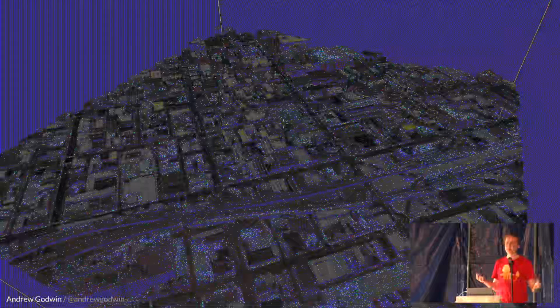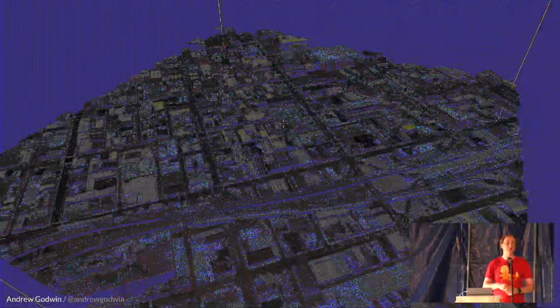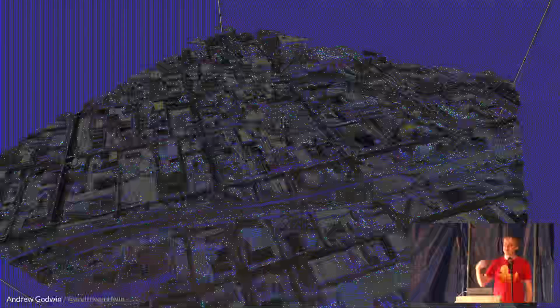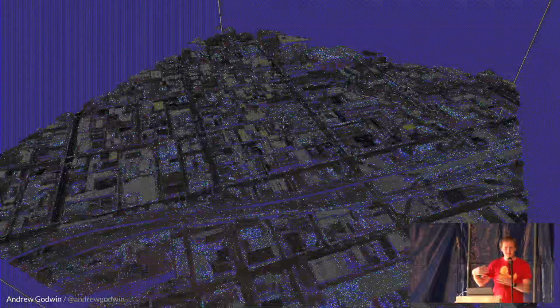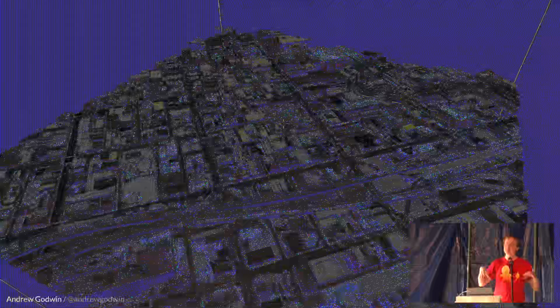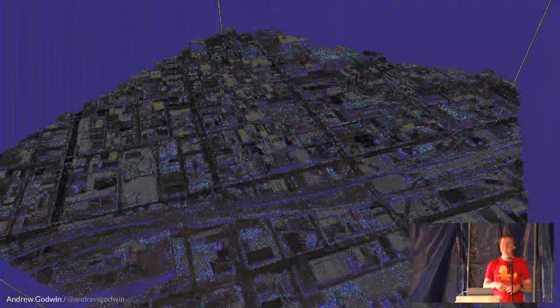So for example, this here is an excerpt from an aerial LiDAR survey of the San Francisco Bay Area. They took a plane, you stick a big LiDAR pod in the bottom of it, and the plane flies in strips over the place you want to map. And the LiDAR device literally scans the ground below it as you go, gets all this detailed information, and with that you can build up a really accurate model, down to often 50 centimeter accuracy, of the place below you. In the raw data here, you actually see the individual crossings and individual parts of streets in the data, and this is the low resolution version.